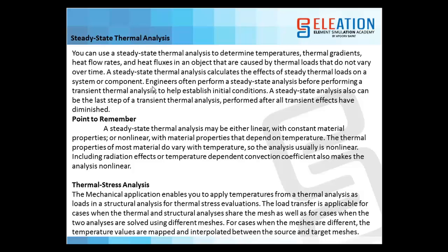So the mechanical application enables you to apply temperature from a thermal analysis as load. So we apply temperature as loads instead of forces or pressure or moment, and calculate structural analysis for thermal stress evaluation. The load transfer is applicable for cases when the thermal and structural analysis share the mesh, as well as for the cases when the two analyses are solved using different meshes. So we can have the same mesh or same model to perform the thermal stress analysis and steady state thermal analysis, or we can have different meshes.